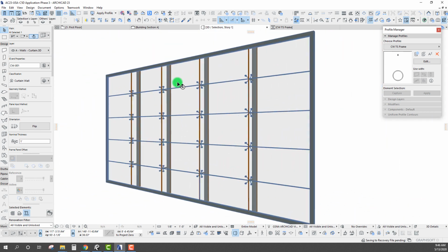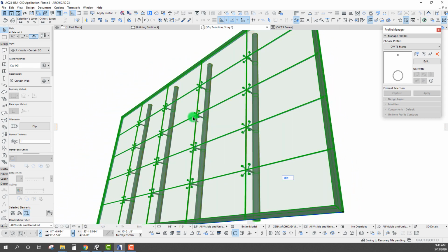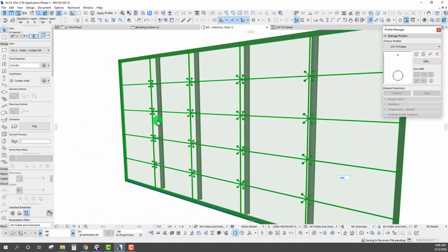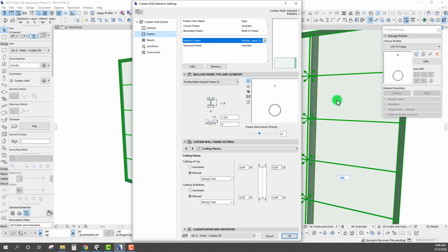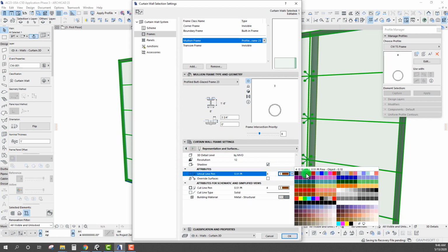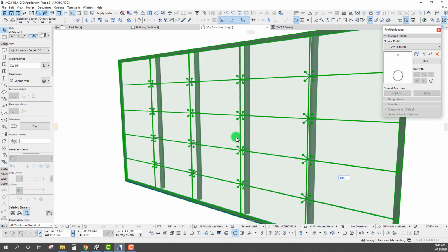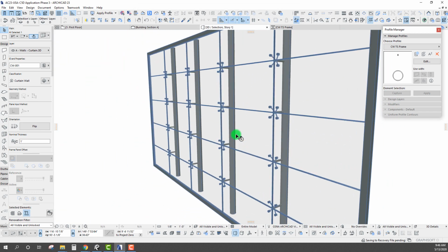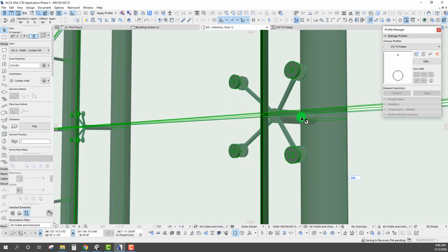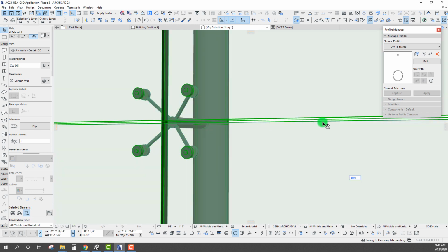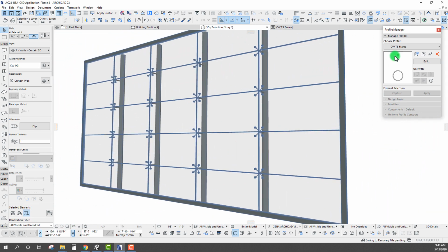One thing I really don't like with this is that contour pen. So let's go in and make an adjustment there. So the contour pens for our frames now are actually going to be in this panel right here. So we'll click over one more, and let's just make that kind of the light blue color there. So that's looking much better. And okay, so last step here is probably we need to add in our sealant running in the other direction.